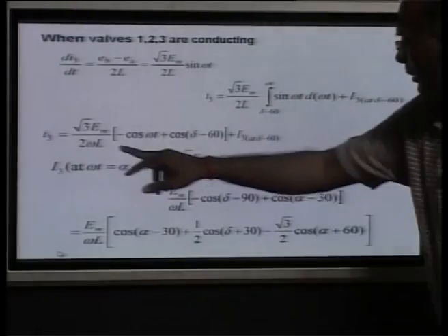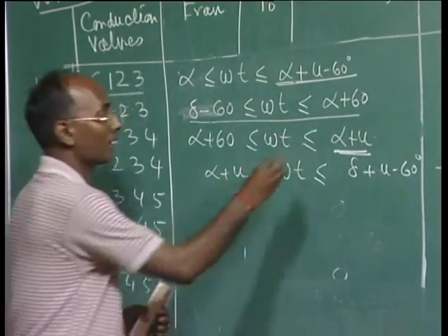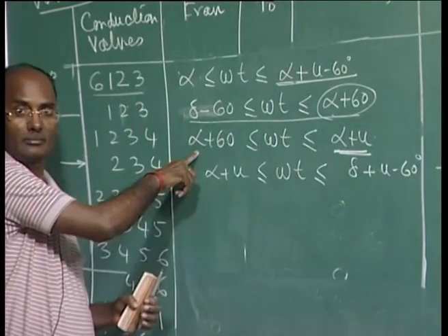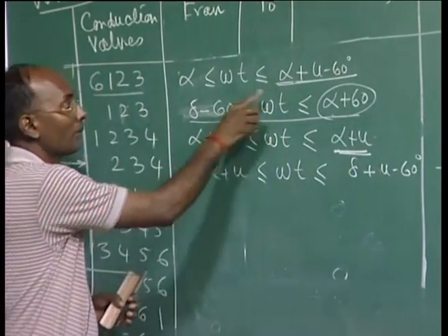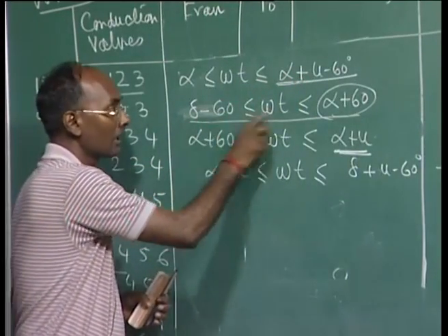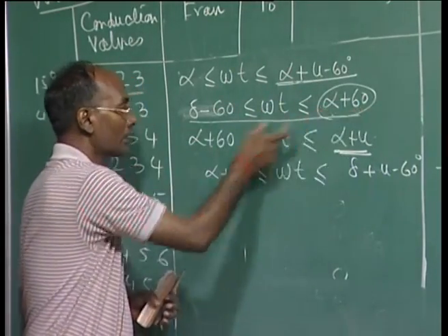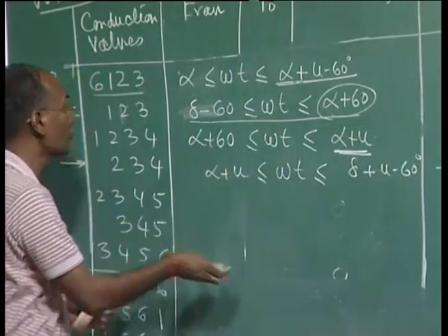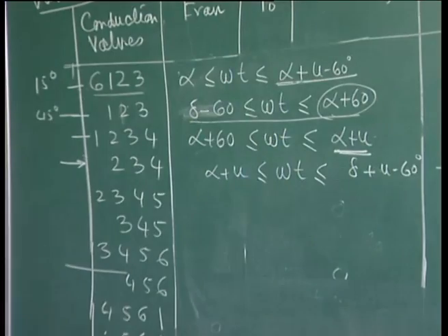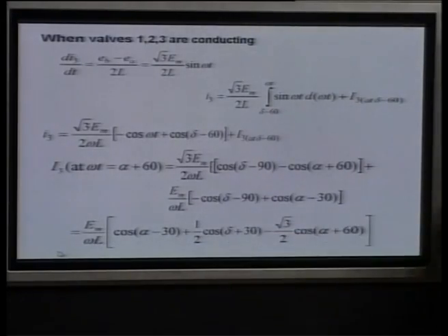you will find you are going to get the current, and again I want to know what the current will be at this value, because that will be the initial current for this phase. So, the initial current for this will be at this point; you just put this value and add it. Here you are deriving the expression, you are adding, and after that you get the current here, which will be the initial current of this phase, meaning we are having the 3 stages. The commutation is taking place, and if you put this value and simplify, you get this I3 at this point.